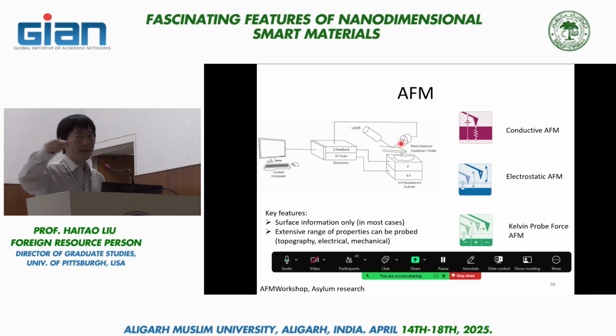And also can scan the substrate in the X and Y direction, and also remember there's a Z direction closed loop. So by doing this consecutive scan, you can create a topography image of the surface. That's the so-called tapping mode.